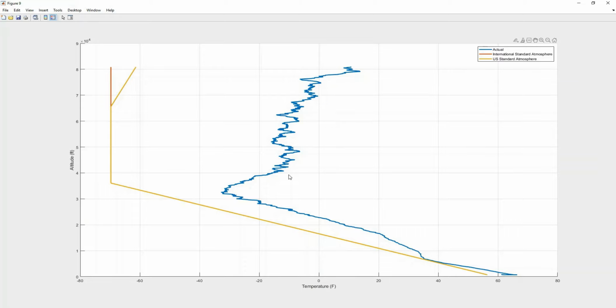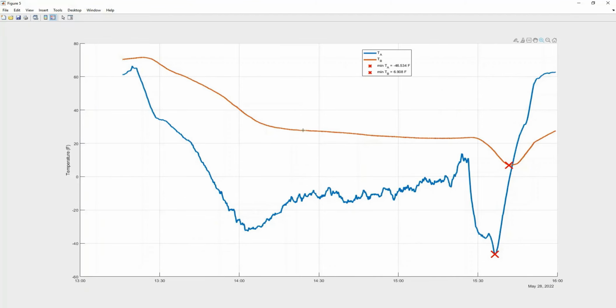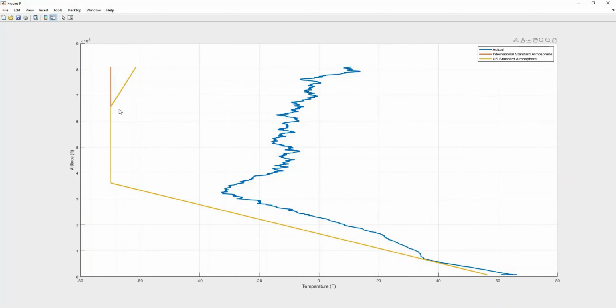Now, one thing that I'm sure you're saying is, look at this, there's quite a discrepancy in the actual absolute value of temperature, right? The trends are there, and we did measure that, but the absolute value is different. So I think one reason for this is, if you come back to our other temperature plot, right there was an interior temperature and an exterior temperature. Remember, we had heaters running on the inside. We had electronics running on the inside. So the interior of the box was much warmer than the exterior. And I think the exterior of the box was also still much warmer than the actual ambient temperature because we were so close in proximity to the electronics and things like that.